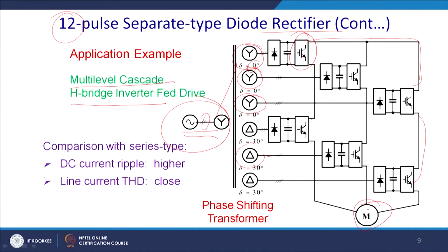Similarly, you require a special kind of transformer to be designed, and if you do not have a bulk demand, then the cost will go up, and commercial viability is a question mark. But here you are not using any special kind of transformer, still you can achieve a very good THD.